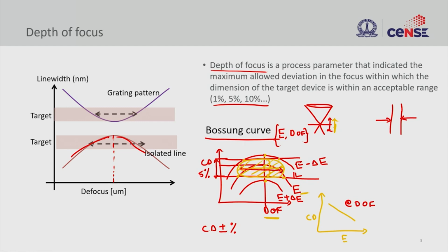You see pretty large windows, right, that you get. And this can be in the order of a few tens or hundreds of nanometers, right, the window can be. And the exposure dose can be 5 to 10% variation, which in commercial systems is pretty tight, but your depth of focus is controlled by your wafer flatness and so on, right, that we saw earlier.